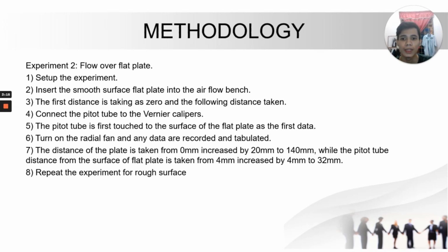The distance along the plate is taken from 0 mm, increased by 20 mm to 140 mm, while the pitot tube distance from the surface of the flat plate is taken from 4 mm, increased by 4 mm to 32 mm. Repeat the experiment for the rough surface.